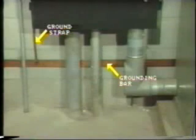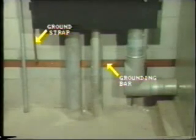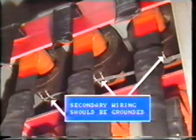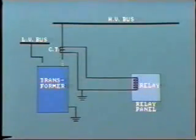The potential of all framework throughout the area is at the same ground potential, so providing safety for personnel working in and around the equipment. Even secondary wiring, for example, CTs and VTs, should be grounded to discharge any electrostatic potential. However, it is very important to remember that these circuits should be grounded at one point only.